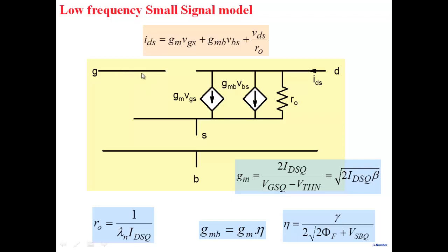And we saw that the voltage has to be considerably smaller than the thermal voltage here, VT. Base emitter voltage had to be much smaller than the thermal voltage VT. VT was 26 millivolts, and much smaller would be maybe 5 millivolts, 2, 3 millivolts and things like that. So in bipolar, if you want your analysis to be valid, you would like to keep it at 2, 3 millivolts, for 10% errors and things like that.